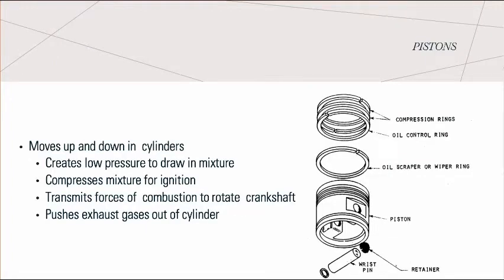And the piston is a composite design with a nodular cast iron skirt and steel crown, and the piston skirt is pressure lubricated to ensure a controlled oil distribution to the cylinder liner under all operating conditions. Oil is fed to the cooling gallery in the piston top through the connecting rod, and the piston ring grooves are hardened for good wear resistance.